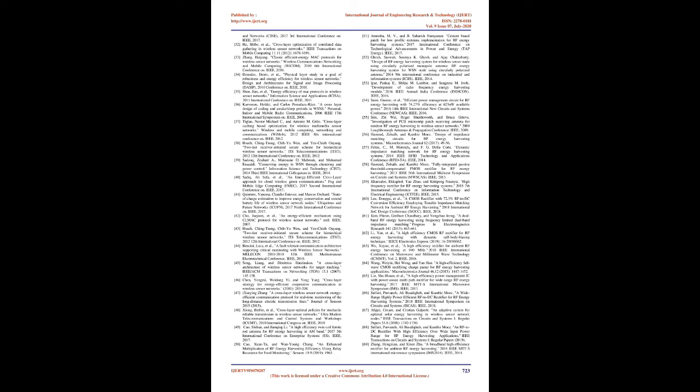3.4 Voltage doublers. A voltage multiplier or a voltage doubler is an electrical circuit that increases the lower AC voltage to higher DC voltage, by using appropriate capacitors and diodes. Normally the voltage multipliers find their application in electronic appliances to increase the required voltage levels, also used in high-energy physics experiments and lightning safety testing.